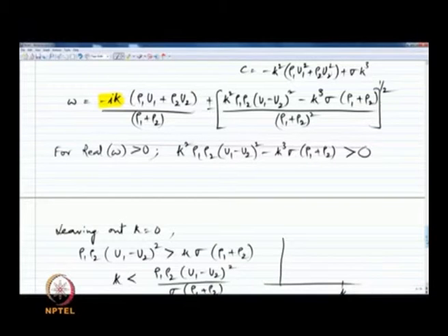So, the interface between two fluids and understanding the physics associated with the corrugation of the interface between two fluids is essential to studying atomization. So, that is the purpose of what we have been doing. We went through the whole linear instability analysis calculation over the past couple of lectures, and we have now arrived at a dispersion relation, which in this particular instance can be written out explicitly as shown here.